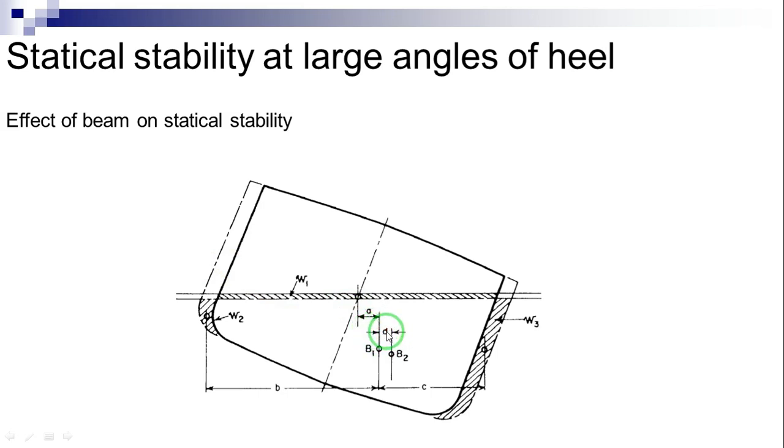The righting arm would be affected also by any movement of the ship's center of gravity caused by the added weight. As a practical matter, the weight change would probably be small and not far from the ship's center of gravity, and the effect of the weight change on the righting arm would be small, if not negligible. Metacentric height, and therefore the righting moments at small angles of inclination, are increased by increasing beam because of the large increase in the moment of inertia of the water plane, along with small changes in volume of displacement and vertical positions of the centers of buoyancy and gravity.